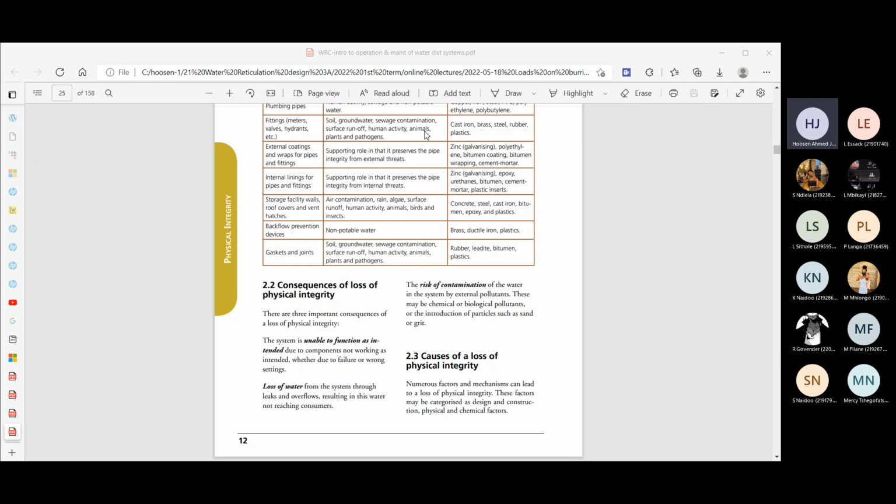If it's a very light soil, maybe 12 to 15 kilonewton per meter cube, usually around 16 to 18 kilonewton per meter cube, depending on the type of soil. In simple terms, gamma is the density of the soil.